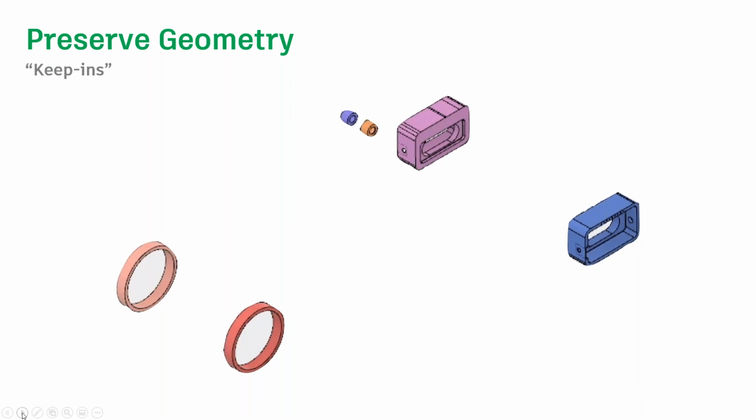So we are telling the solver, okay, do whatever you want, but in the final outcomes, I need to have those regions as I have created them. And this is because, for instance, you need those regions for assembling the part that has been designed with generative design to the other components of your assembly.